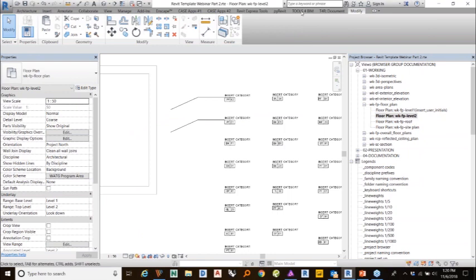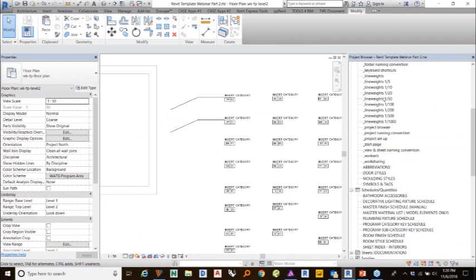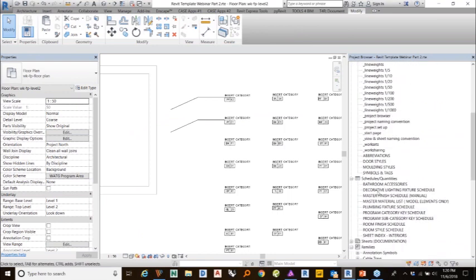If I put these in a view, I want to quickly show you how I built a schedule off of this. This is called my master finish schedule, and I put manual in there to forewarn the people using this that it's something you manually place, copy and paste, and manually change.